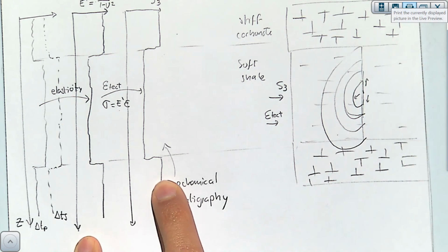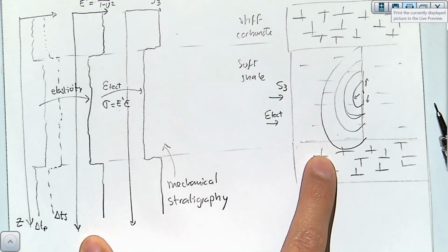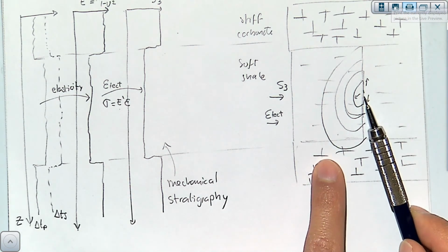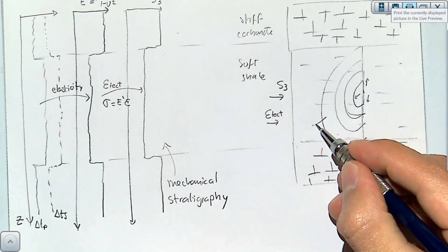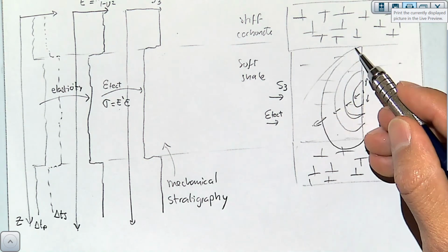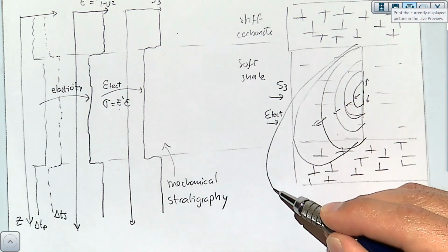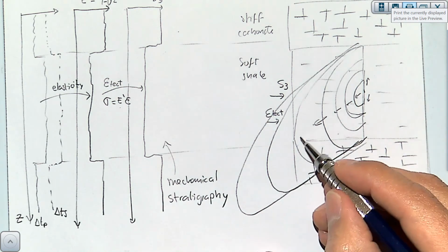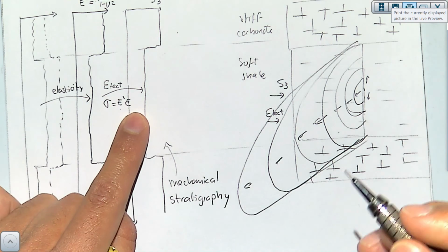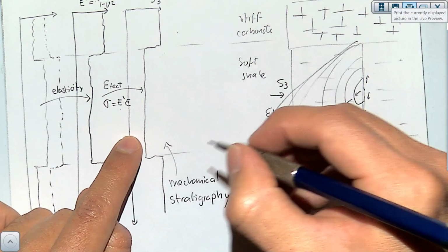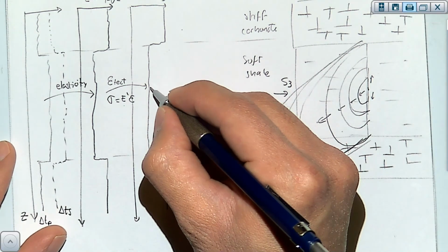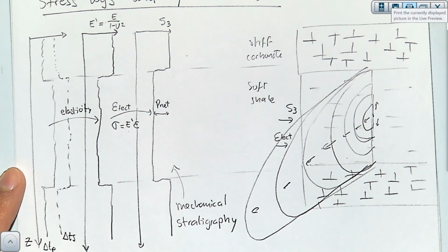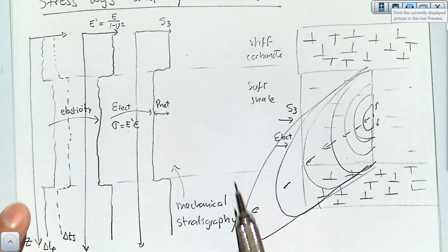And now the fracture might go onto these layers, which have higher stress, or might continue propagating on the soft rock, but now instead of growing up and down, it will just grow in this direction, and it will always grow within the soft shale as long as the net pressure here has to be smaller than this contrast.